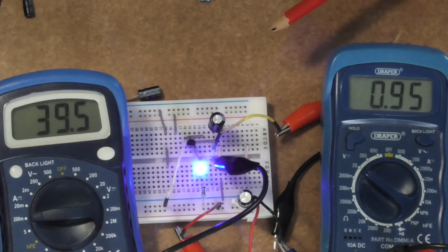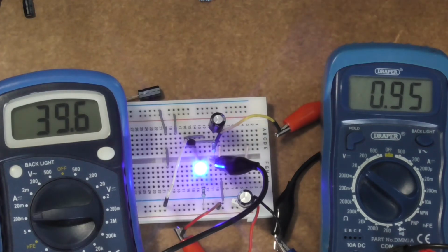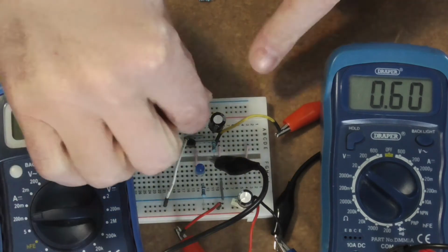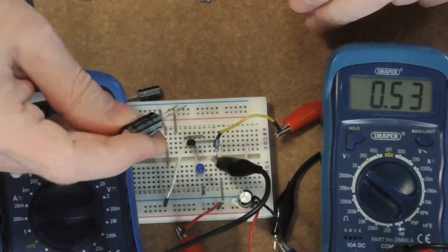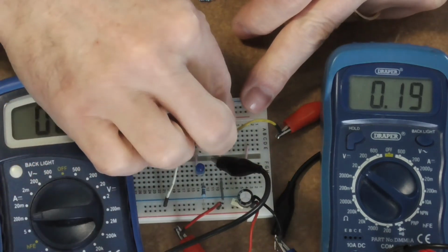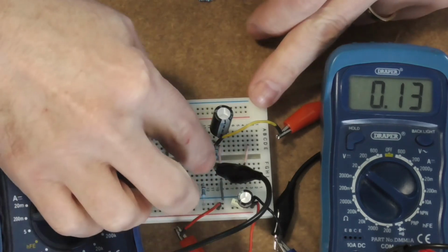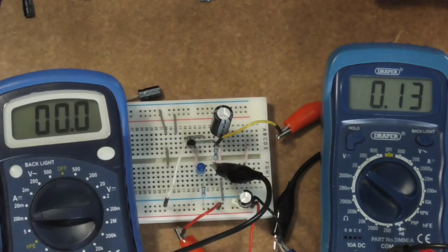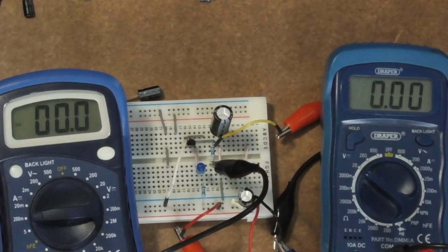And again, it's almost instantaneous, because this resistor is allowing through enough current quickly enough, and voltage, to charge up any capacitor quite quickly. And I expect it'll still be the same even with this whopping 1000 microfarad capacitor. So get that in there with this 100 ohm resistor, and discharge that one. Turn it on. Yeah, same again.